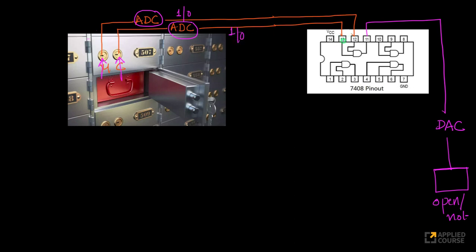Now these two values, this C value, this is the customer, this is the manager, the Boolean representation of whether these keys are valid or not, go into pin 12 and pin 13 in the 7408 chip. Each chip has a unique number. Nobody remembers these numbers by heart. You Google search for it in the real world.